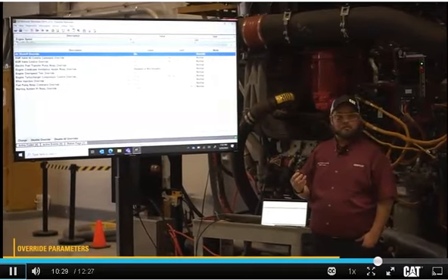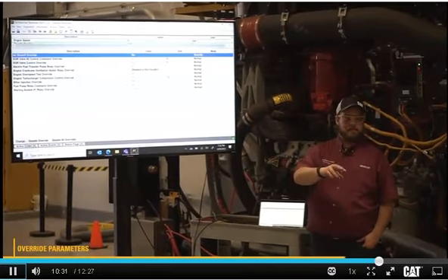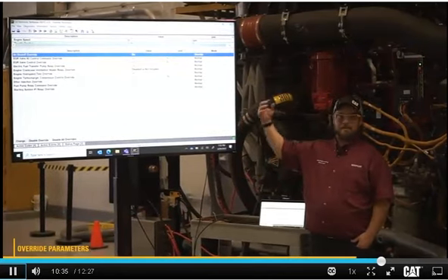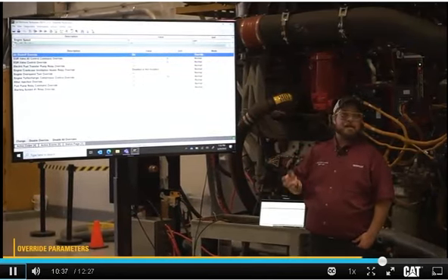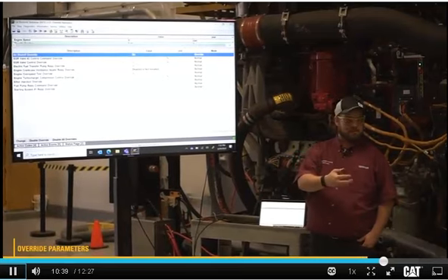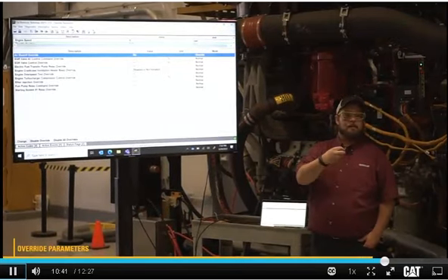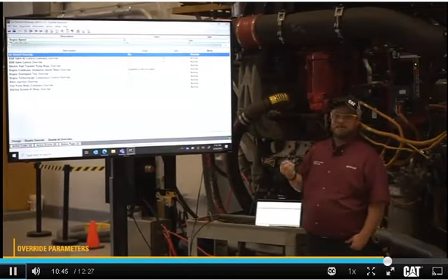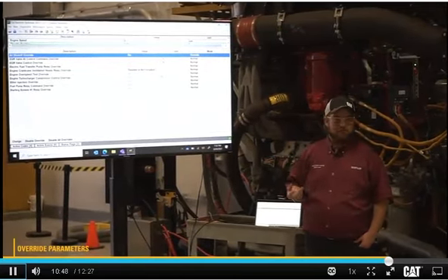So if I were troubleshooting this, again, if I had a -5, I'd have made a short circuit in that harness, ran this test, and then see for my code to change, and vice versa. If I'm dealing with the -6 code, then that's a short circuit, I would make an open circuit, activate the output this way, and see if my code flips.